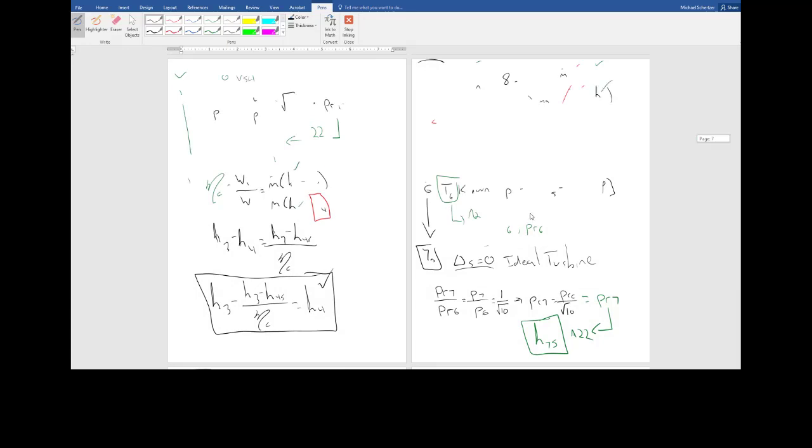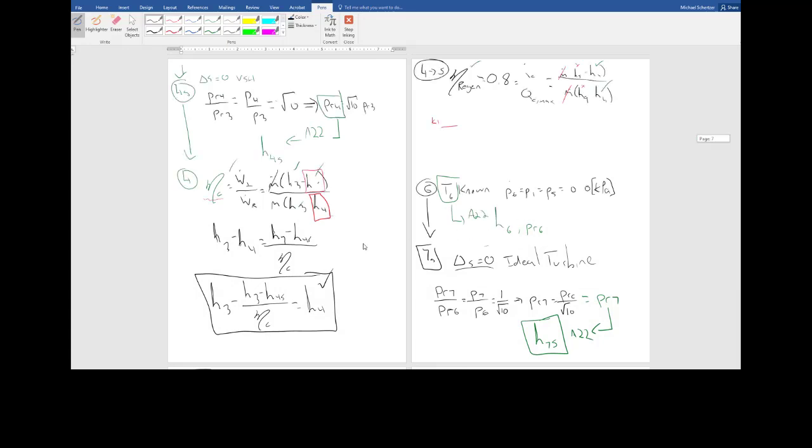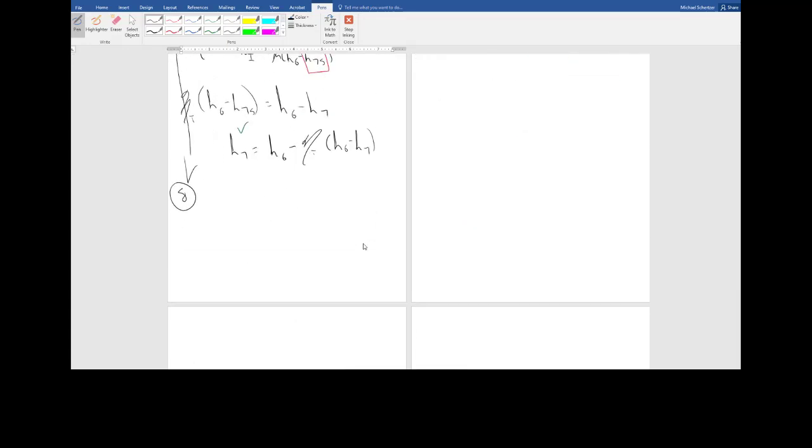So now this ends up being just like, remember how when we went through the compressors, it was like a repeat when we did the second compressor? This is the same thing, right? So now here we know T8, right? Because as we go from 7 to 8, this is still, and then we know that P7 is equal to P8, right? And because I know T8, I can go through on table A22, and I can find H8, and I can find PR8.